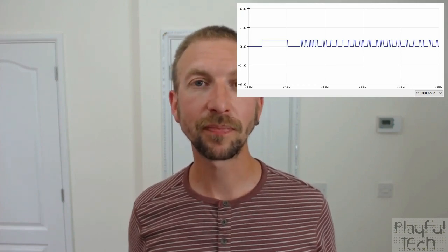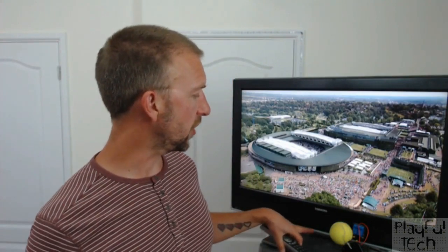And that's what we're going to do in some of the projects in the rest of this video. So here's one idea for a puzzle you can do using infrared. Here I've got a family television and I've got the infrared remote control that goes with it. Now I've not modified the television itself at all, but underneath the front bezel here I've placed one of those infrared receiver modules I described a moment ago.